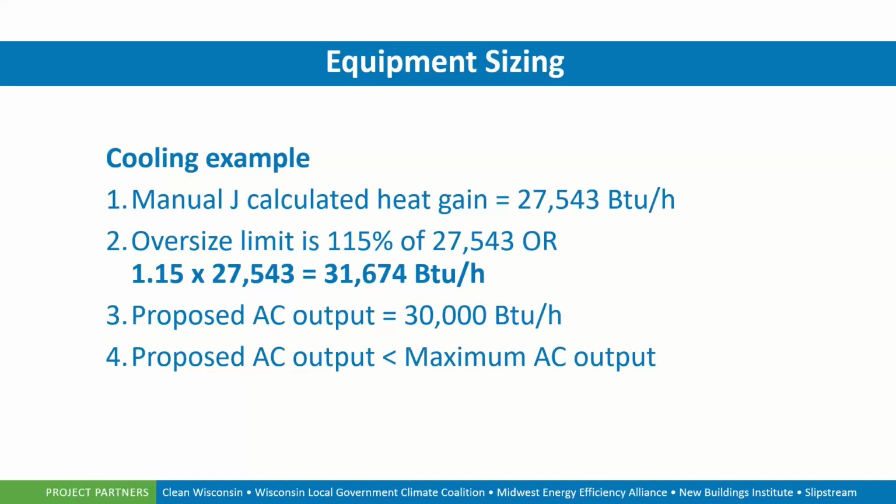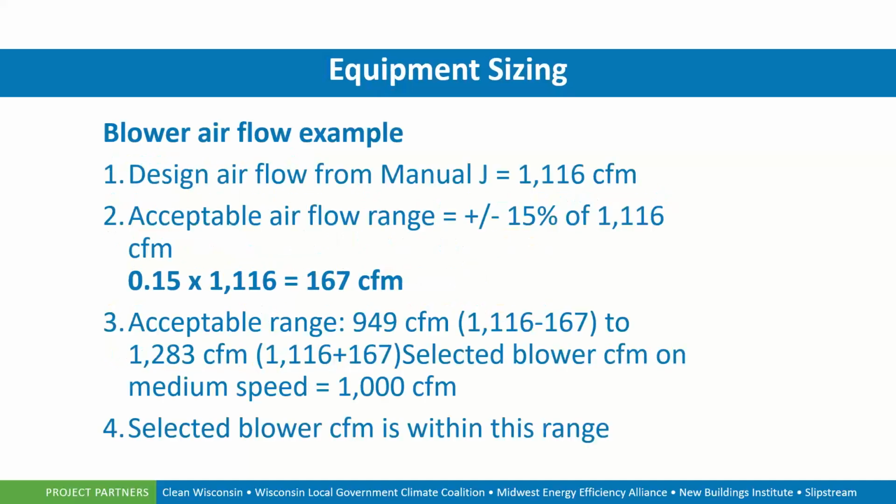Latent heat is the energy required to change the state of a substance without altering its temperature. So once we reach 32 degrees Fahrenheit with ice, we then have to apply additional latent heat to change the ice to 32-degree water. So the sensible number is what we're looking at to overcome with our heating or cooling loads within a home.